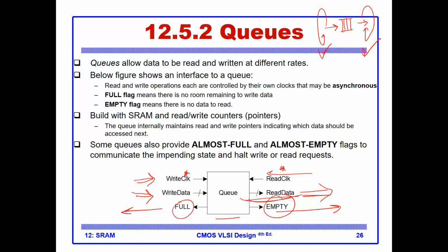In advanced FIFO design, you have an almost full indicator or flag and almost empty. And the reason is that in some of these fast systems, to indicate the flag, you might have data which is in flight, because the system already sent out this data to be written. You want to send this indication very early, almost like throttle down.